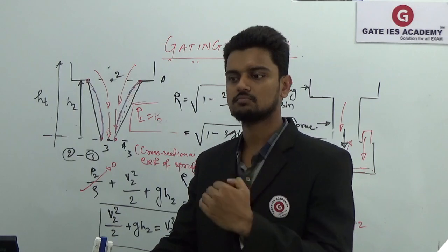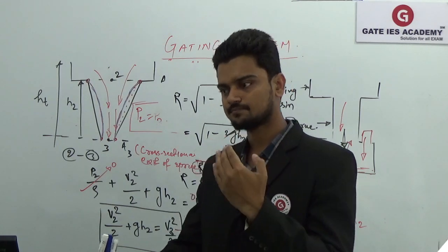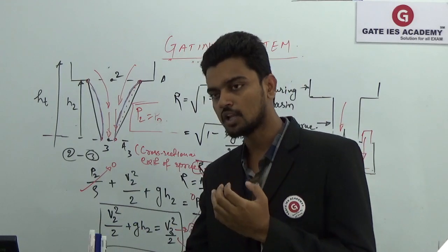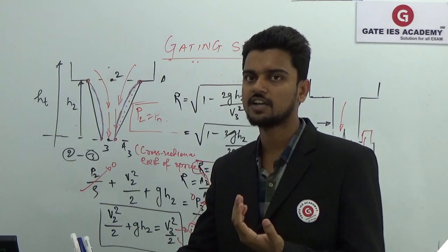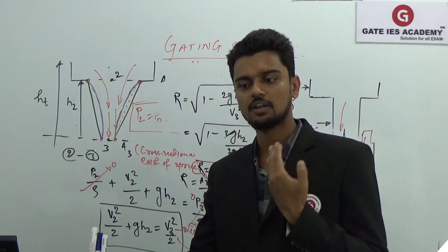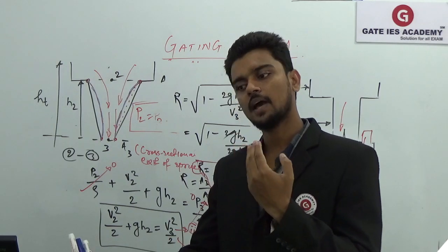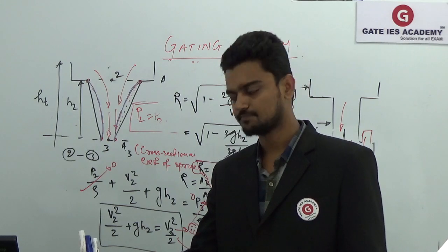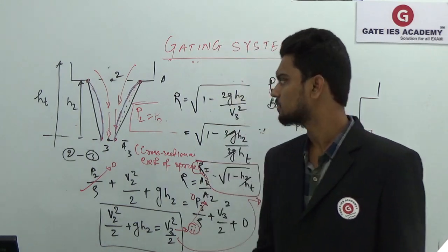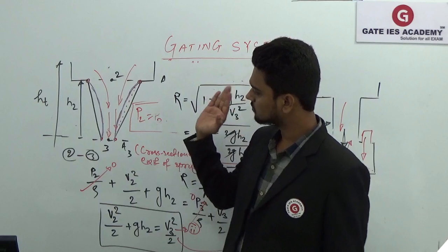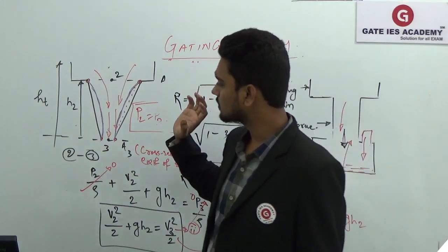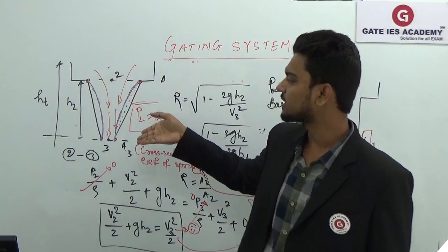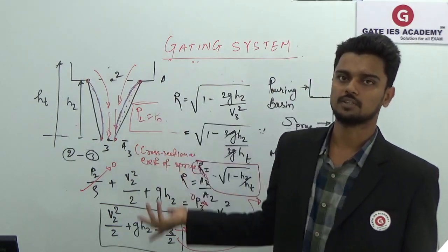So at the exit, that nozzle has the smallest cross sectional area. So at that point, the velocity will be maximum, and obviously pressure will be minimum. Okay, the same concept. So to ease manufacturing, we are making the straight taper in place of the parabolic shape.